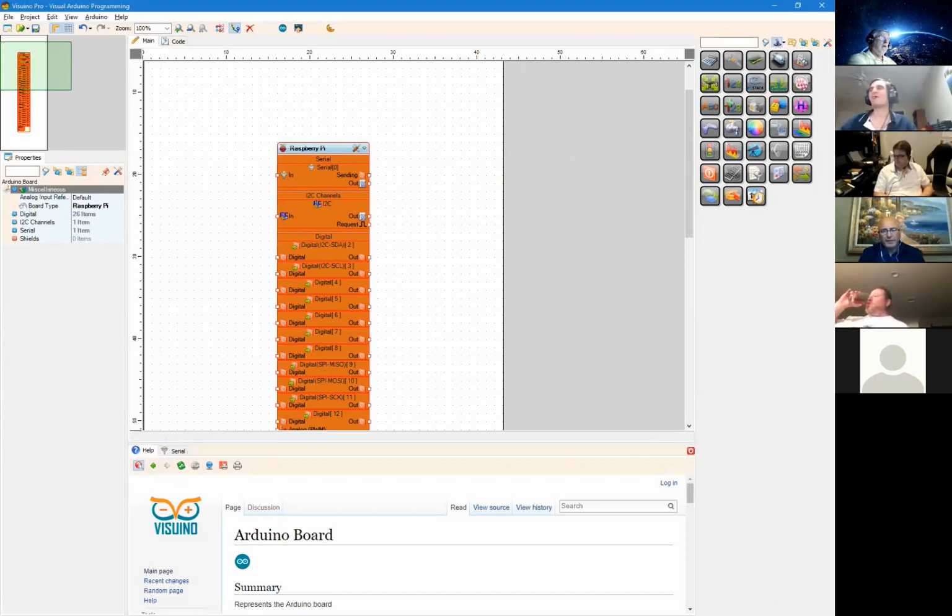It is fast. It has a fair amount of memory, a fair amount of capabilities. Obviously, it has Bluetooth. You can technically make it work in both Bluetooth LE and Bluetooth Classic, even simultaneously, though it's a little bit of a complex task. And it has Wi-Fi built in, and it even supports secure sockets on the client side, at least. So I would definitely say ESP32.